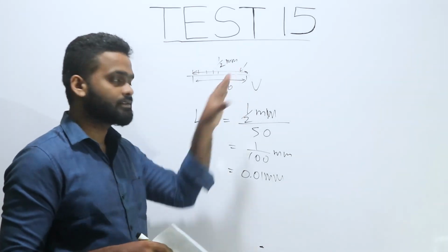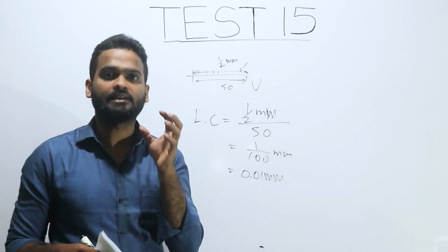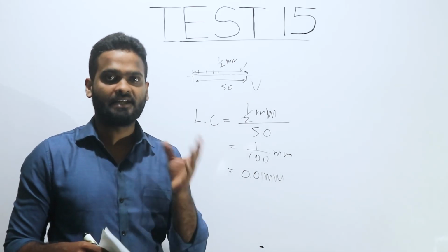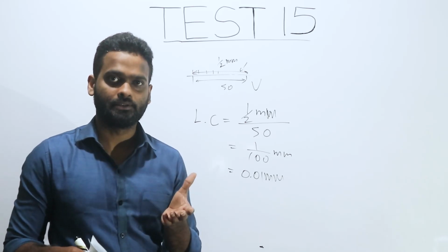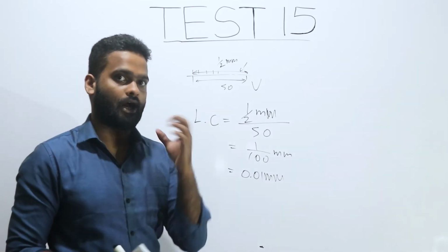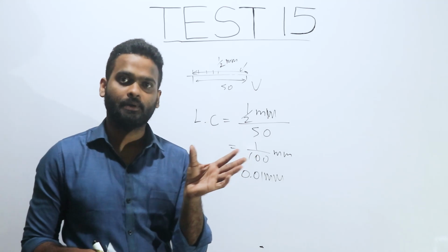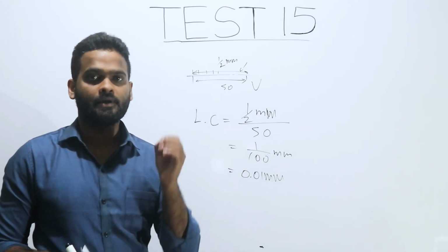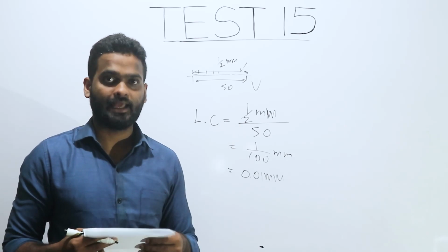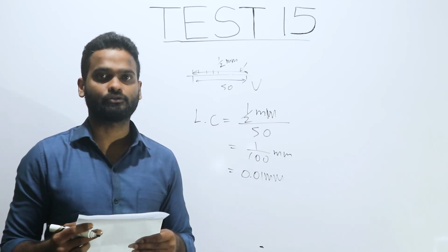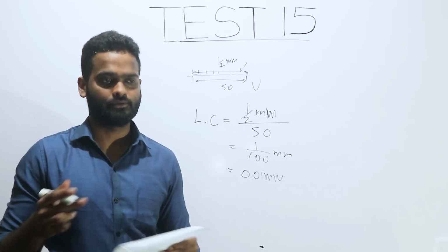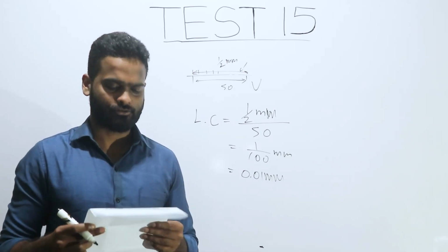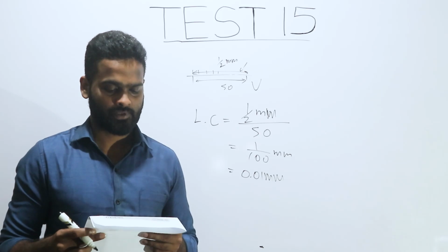This is the vernier scale contained in a traveling microscope available in the lab, where 49 half-millimeter parts are divided into 50 vernier parts. You should know that if you did experiments using the traveling microscope in the lab.